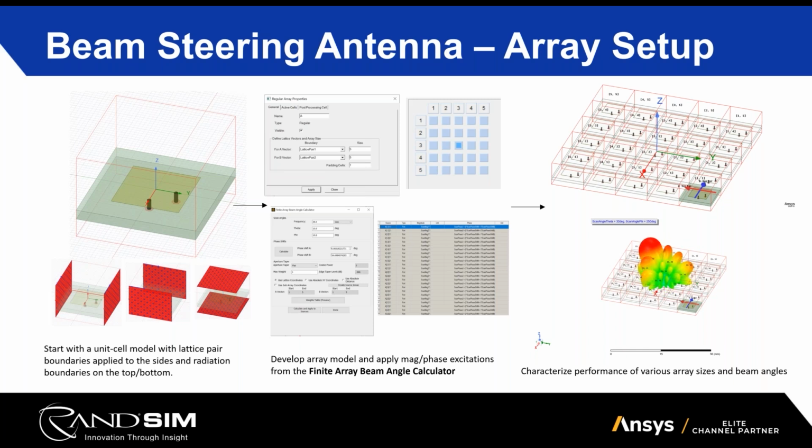The process that we do that through within HFSS is we start with a single element. This is always a good starting point. It allows you to optimize and make sure that the antenna is well designed for the frequency you are trying to design it for, by itself. Ultimately, you want to make sure that your patch is the right dimension for the frequencies that you're operating at. Or if you wanted to get more exotic with it, clip the corners or add an additional patch, or whatever your type is. Starting with that single element, you create what's called a unit cell.